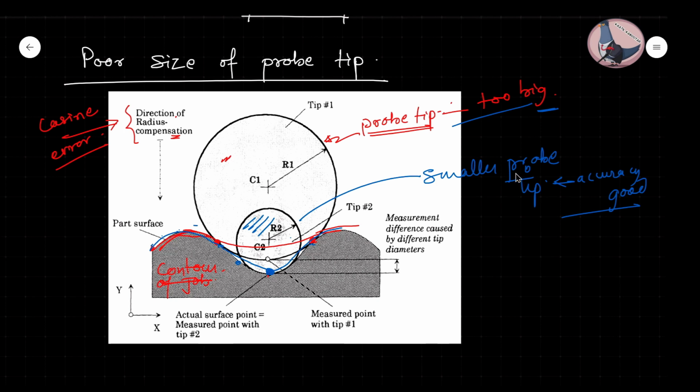So which one should you choose? The larger one or the smaller one? In general, people tend to say the smaller one, that accuracy is very important when we are doing dimension inspection. Then our aim is to obtain the deviations or the very exact dimensions, but it is not true. It is partially true that we use smaller probes, but we try to optimize the size and we try to maximize the size, because when the probe size is bigger, you will touch fewer points and the data that you obtain will take less computational space.